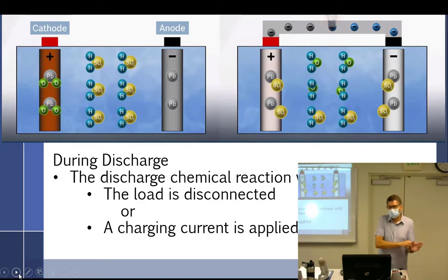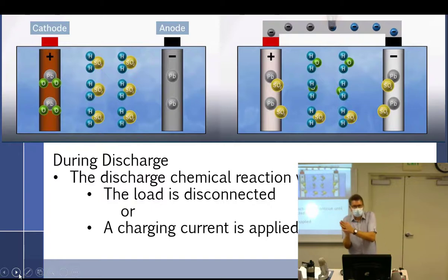All right. Then I say, I better start the engine. So, hopefully you turn off your loads, and then you start the engine, and you bring them all back on. Turn on the alternator, and you're going to see that ammeter swing hard to the positive side. Let's say it goes to 20. That's how many amps are going into the battery, not how many amps I'm using through the whole aircraft. And you're going to watch it slowly go down till it's almost at 0.